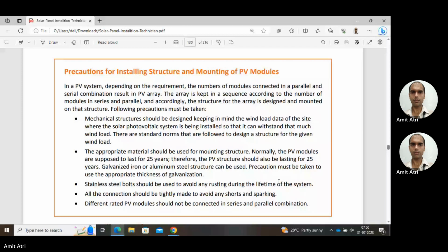Yes, the connections, no type of loose wirings. Also the metallic objects should be properly insulated. Charge should not leak. Short circuit should not be there. Proper earthing should also be there in our solar system.